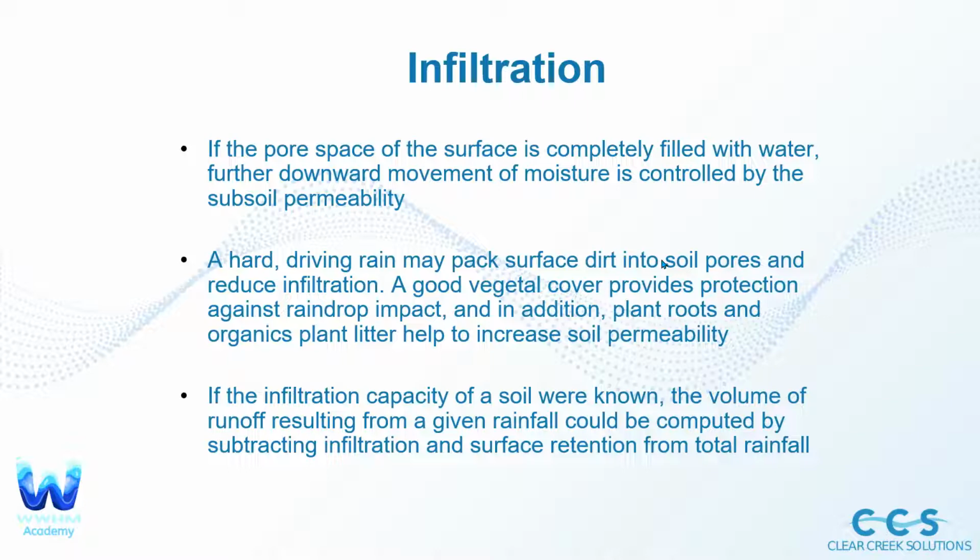It's when that water runs off in large volumes and over lots of different occurrences that we start to run into issues when we come into project development. If the infiltration capacity of a soil were known, the volume of runoff resulting from a given rainfall could be computed by subtracting infiltration and surface retention from total rainfall.